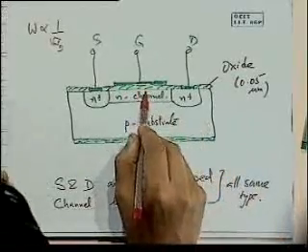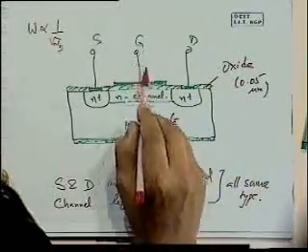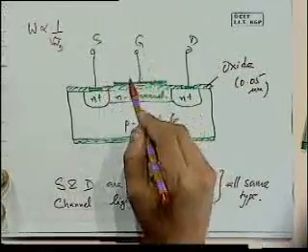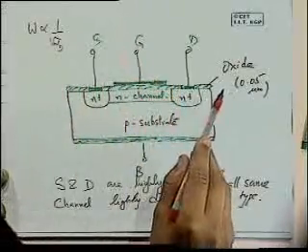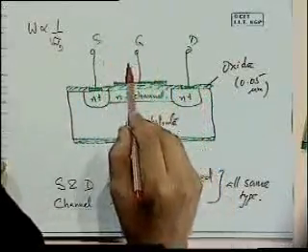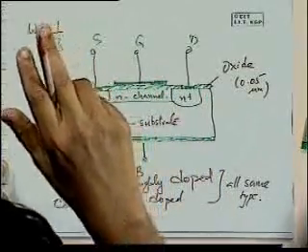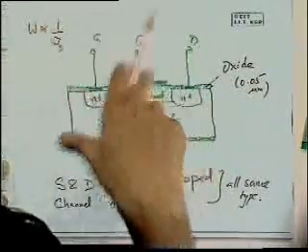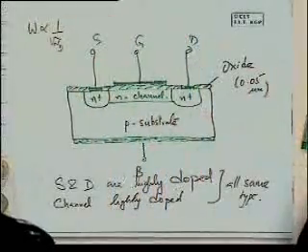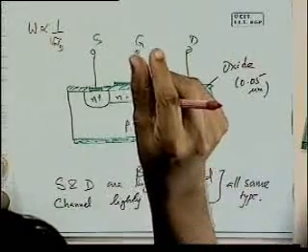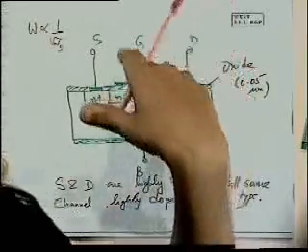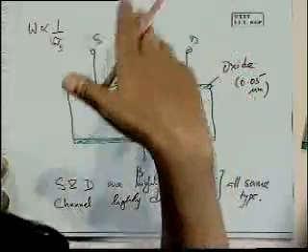And because of the presence of that thin layer of oxide, the impedance there is large, and so gate current, which is really loss, if a current goes from source to gate, that's a loss in terms of the current that is going to drain, that is reduced. The same was the case with the BJT. If it goes from the emitter base and flows in that circuit, any of the recombination there was a loss instead of going to the collector circuit. And so if the base region was lightly doped, we did not have losses there. The same kind of idea. Here also impedance is high, so very little current will flow in that. It's just going to modulate things, but it's not going to have much current flowing through that circuit.